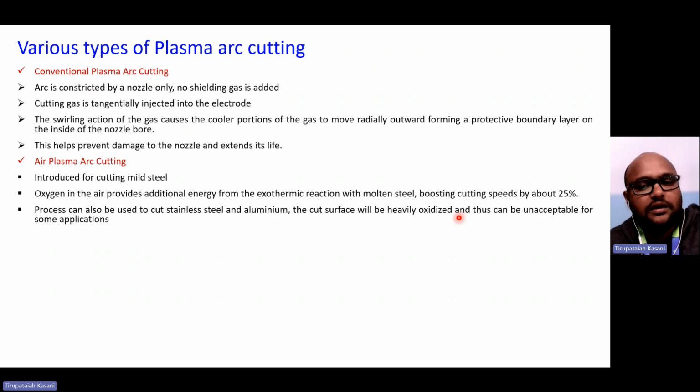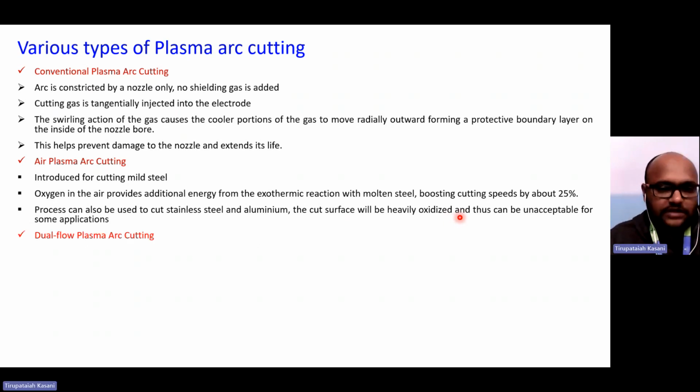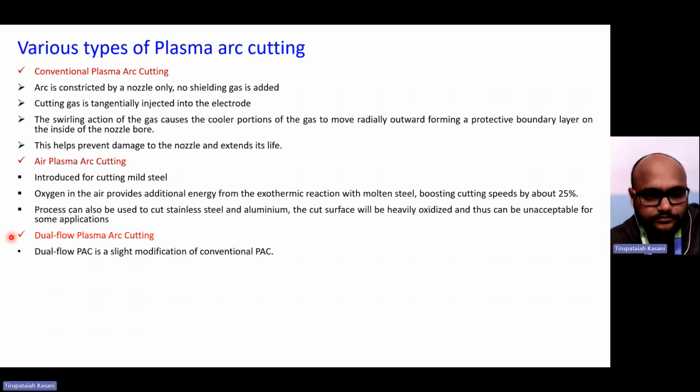That is the reason why, for mechanical characterization of the metals at the cut regions, those metals are mounted and polished to remove the oxides and debris and to observe the grains and grain structures. That is one kind of reason for polishing.